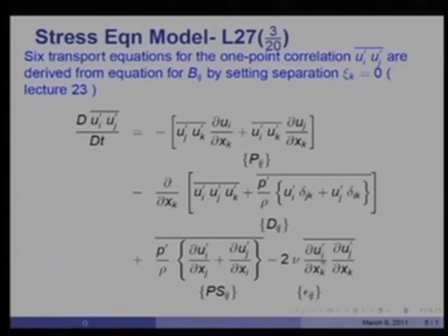and it would be different in different directions. Now, if you notice, this equation is a differential equation mainly because of the convection term and diffusion term. The rest of the terms are simply sources: the production term, the pressure strain term, and the dissipation terms are simply sources.